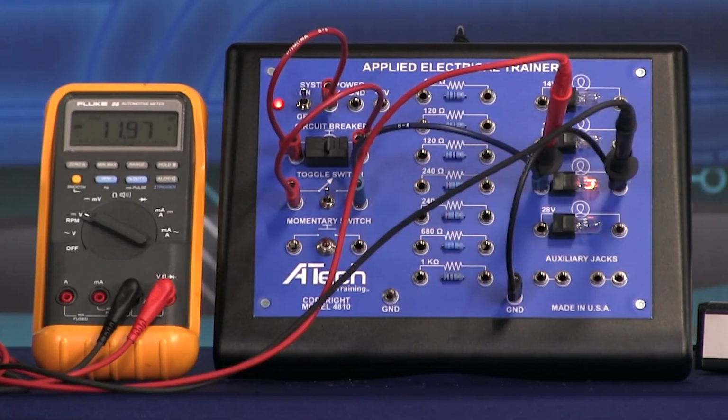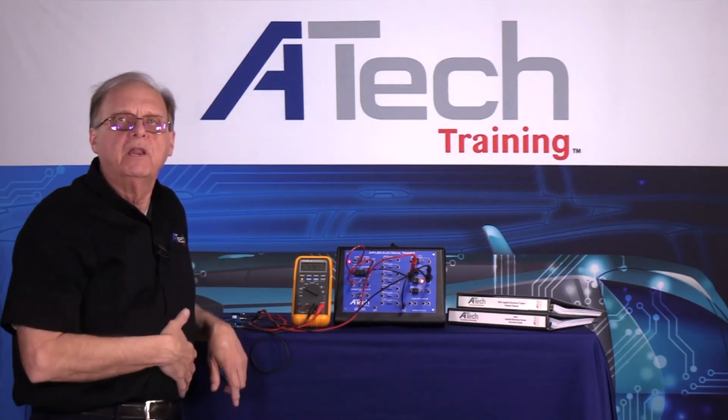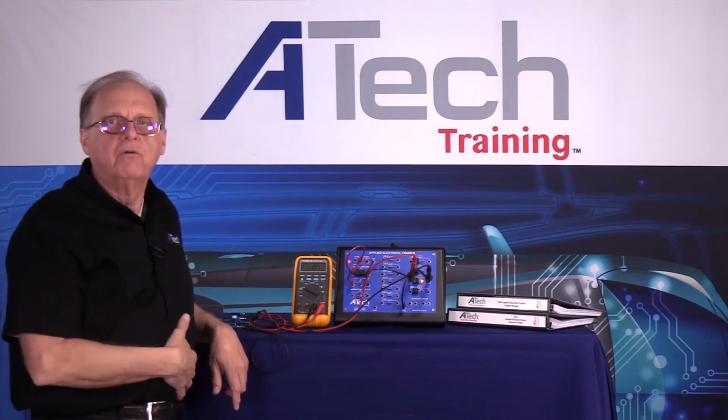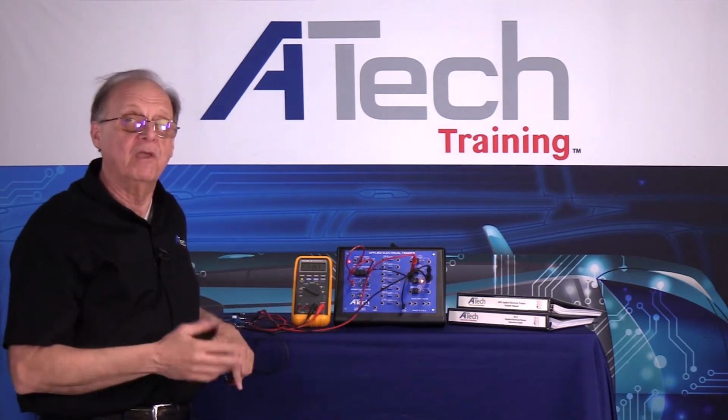Notice what it says. I dropped 11.97 volts. That means that circuit is working properly. Now, if this was a dim bulb, what would that indicate to you? It might be the wrong bulb. A do-it-yourselfer sometimes doesn't always put back what they should into a circuit. It looks the same, so they put it in.